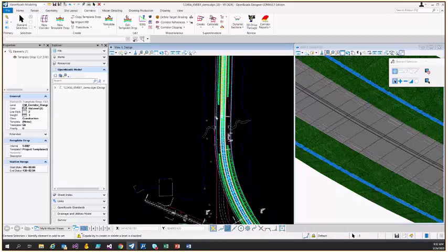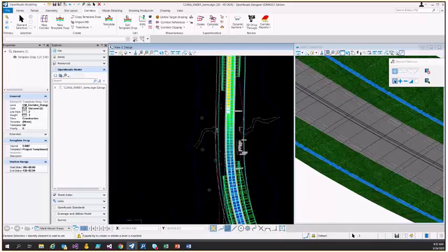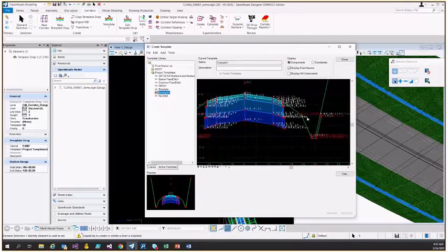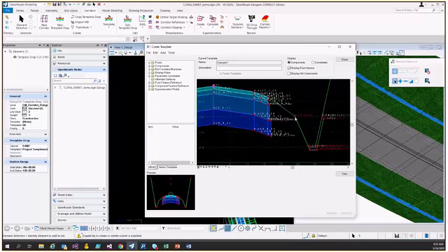So what we'll do now is create that fixed ditch template, which I already did. So here it is. I already made it. One thing that I wasn't quite happy with is when I have the left and right sides, the name came in adding the prefixes, but my parametric constraints, it just added a dash to denote the side.